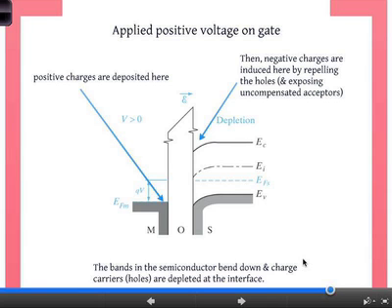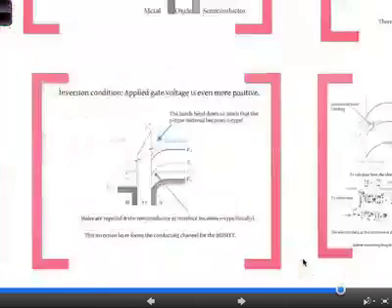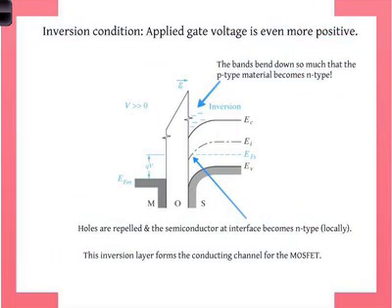So as long as you have a few electrons and some of the holes are gone away, you have the linear regime. Well, you can have cutoff if you don't have enough carriers, so you have some regime where you have no current flowing. At some point, when you increase the gate voltage further in the positive direction in this case, you get enough carriers that you start turning on the current. That's the idea, which is what happens here. That's the inversion condition.